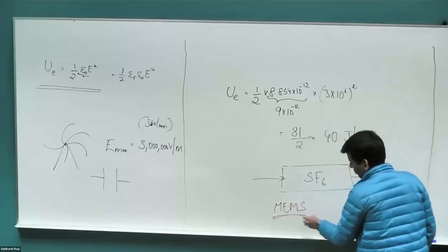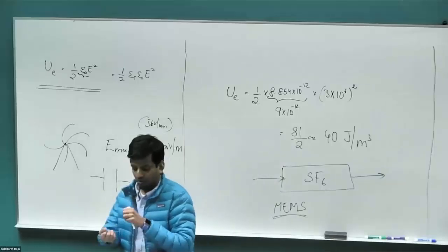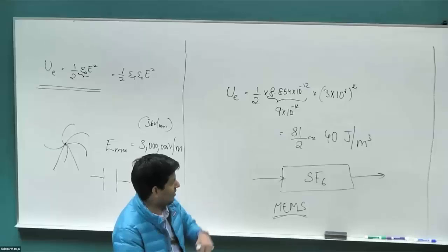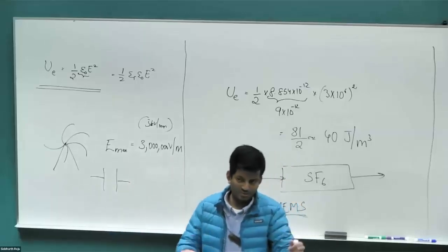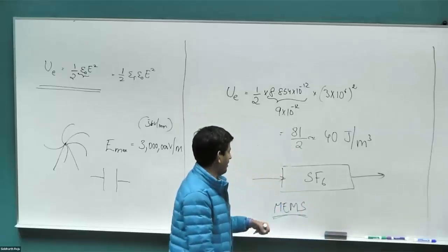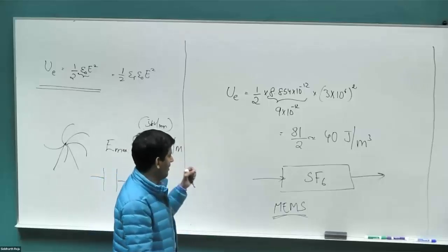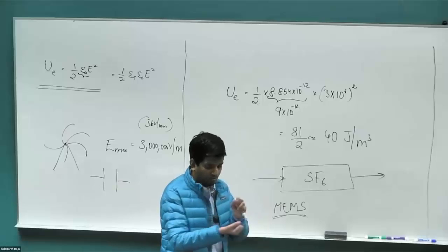And there's a lot of research going on where you have tiny robotics that we want to put into our blood, within our veins, and they have to navigate and go somewhere. You typically can't put a DC motor in there, right? You can't take your own energy source, your own commutator, your own control, all of those, and navigate. But electrostatic motors typically can be made extremely tiny, and they can produce sufficient torque to operate on whatever they are trying to do.